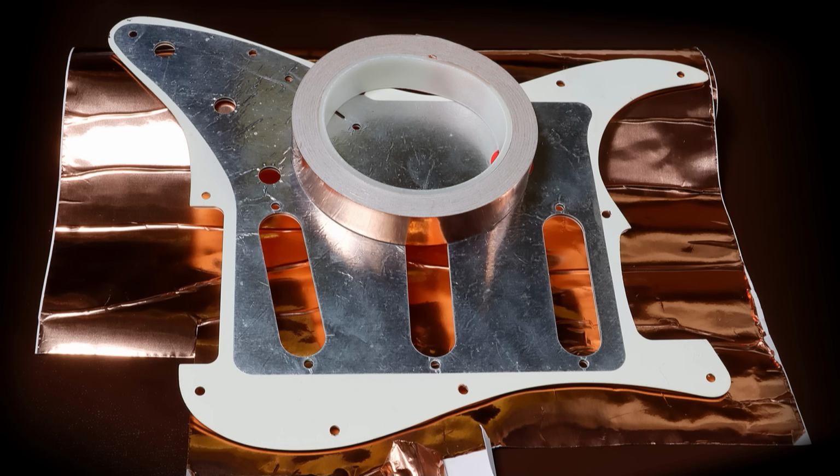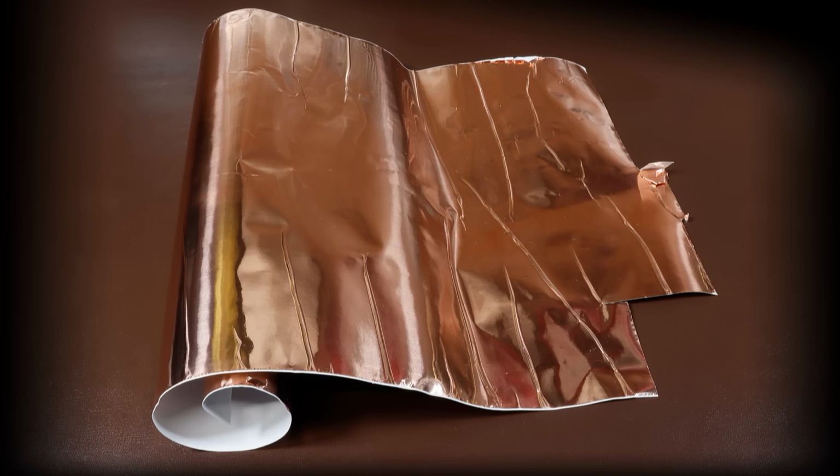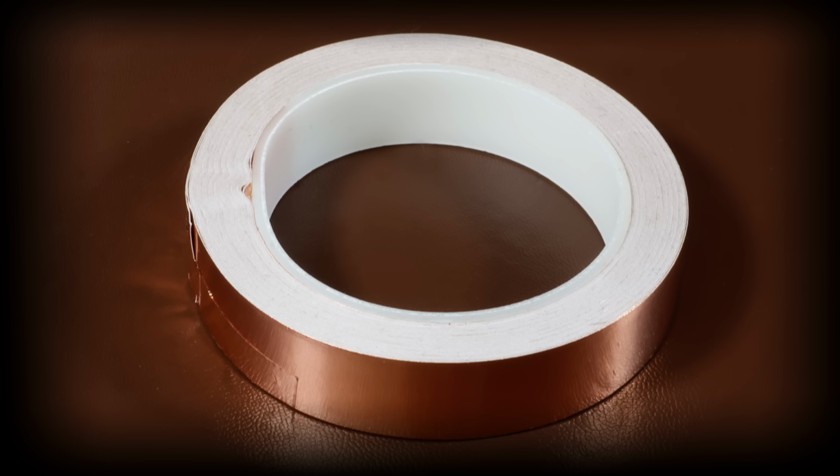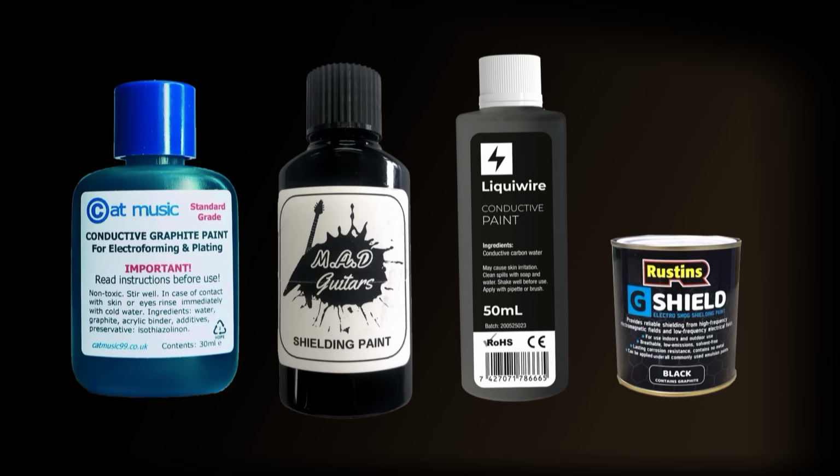If you want to upgrade the screening on your guitar, it's really easy to do. You can buy screening film or tape, and it comes in multiple materials. Copper and aluminium are the most common ones, and you can get screening or conductive paint, which is usually graphite based. And many guitar makers use this, so sometimes it isn't obvious your guitar's screened because they've used the paint.